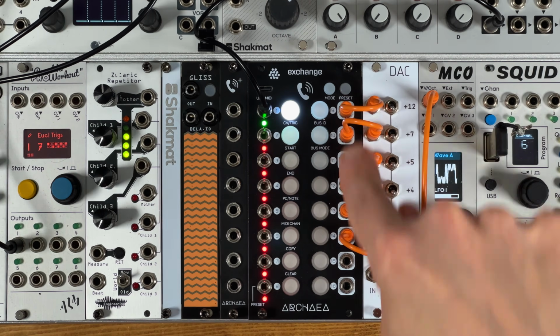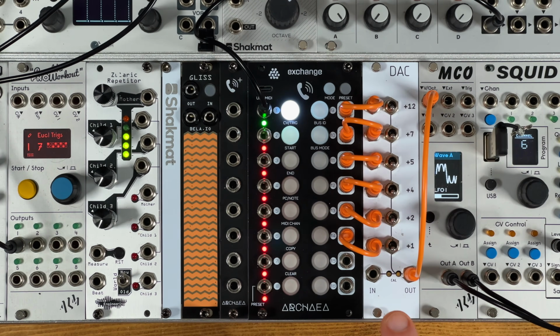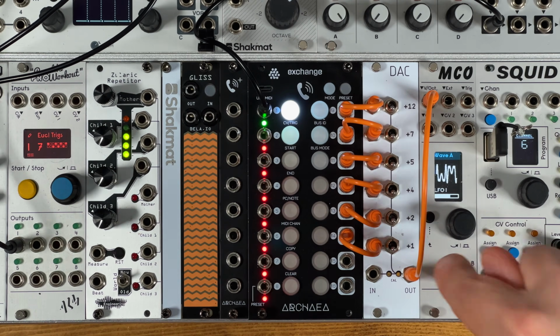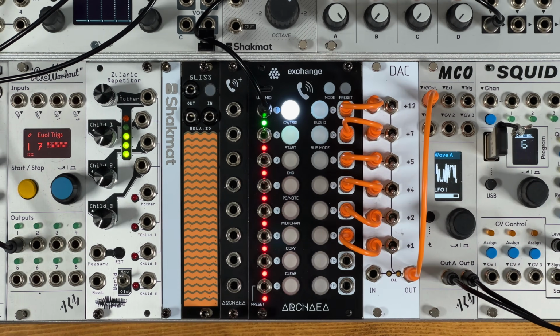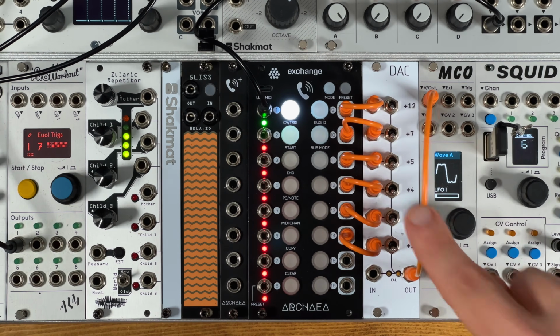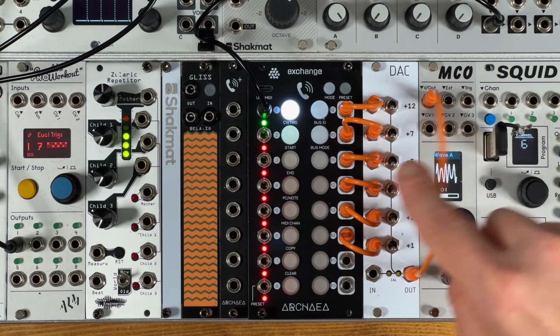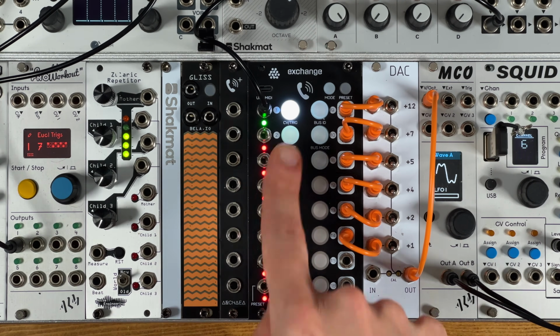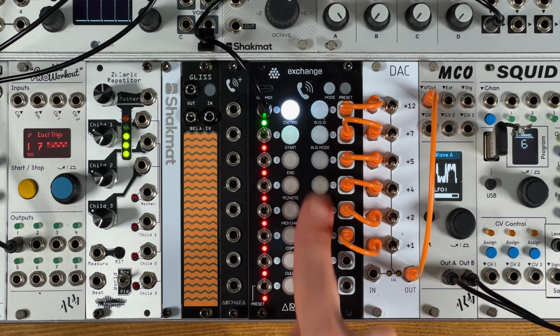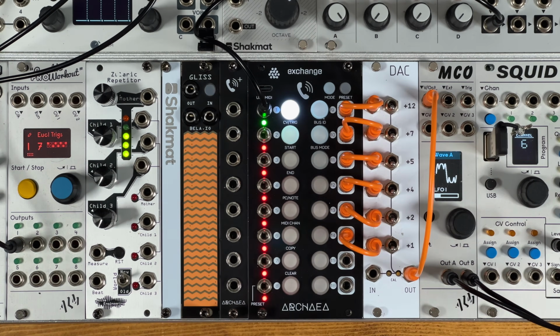And then I'm going to patch the first 6 outputs to this DAC module from Beers. What this does, whenever it gets a high gate at any of these inputs, it adds the corresponding number of semitones worth of voltage to the output. So basically by turning on different configurations of these 1, 2, 4, 5, 7 and 12 semitones, you can create any musical interval you like, and effectively you can then create a pitch sequence at the output by turning them on and off. So by routing that 5 volts using these buttons to these 6 inputs of the DAC, I can create different notes. Let me show you what I mean.